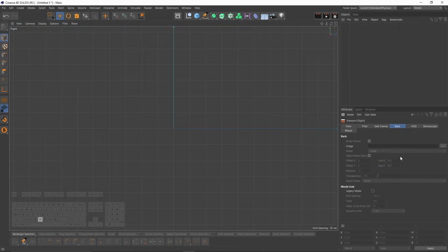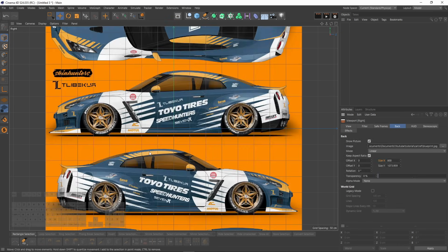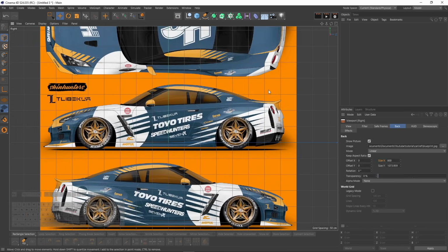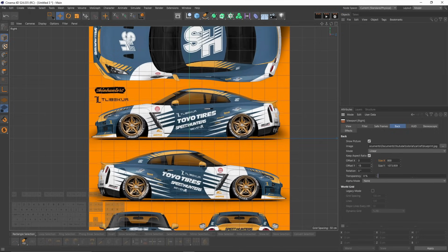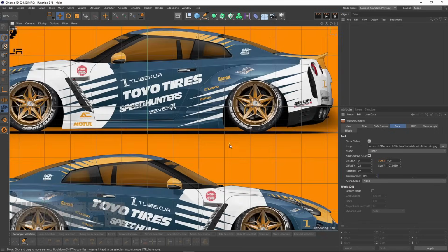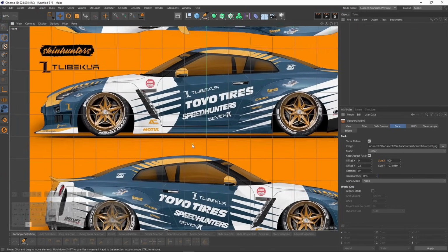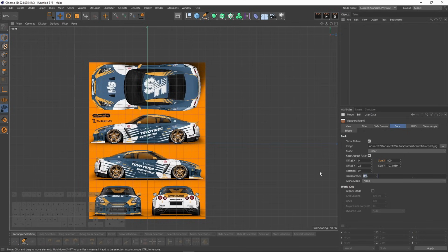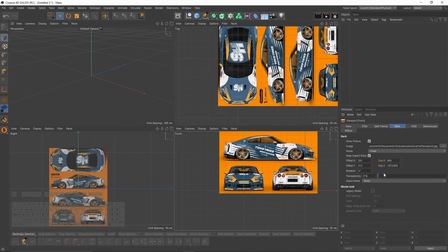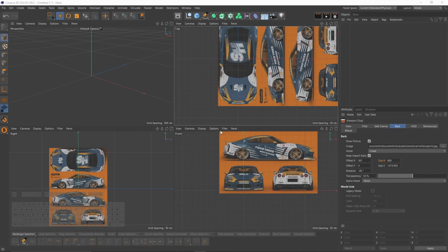Now let's go to right view and paste that same image plane. This time I will use that side of the car. In reality it is the left side, but I am using the right side, so let's make the wheels sit on the Z axis on the floor. Alright, let's increase the transparency so you can see better. Now I will make the final adjustments for the image planes.